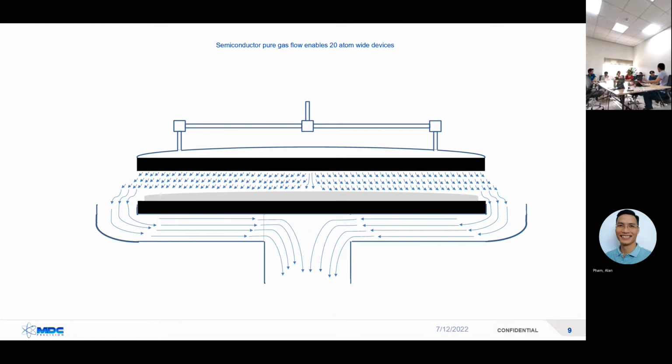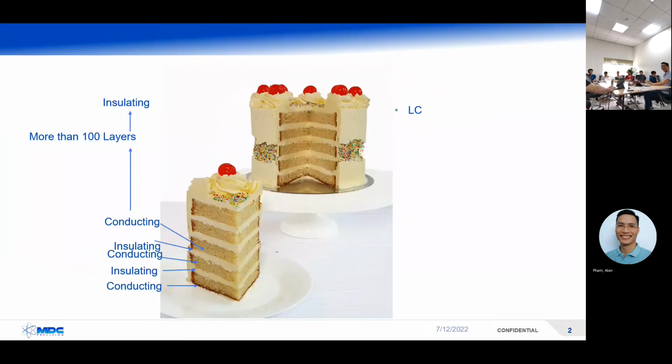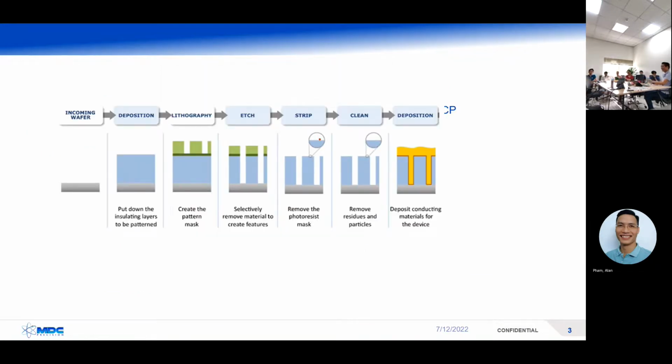We prefer concave or convex welds, or what would be the problem with it? You actually want the weld on the inside of the tube to be not concave or convex, just about as flat as you can, and the diameter is the same width. Yes, always with tubing, the more flat, the better. Make it 100% flat. So that's the simple concept, layer cake, right?